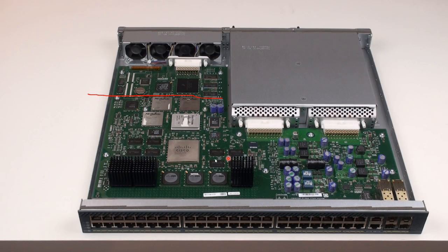On the side, these are all probably memories like SRAMs, those GSIs, or the Samsung chipsets we have here. They are all memories, probably cache or buffer or something. And here we have some more chipsets which are proprietary to the function of this particular switch model. I think these are network processors, for doing different functions like faster packet manipulation, or changing the information in the packets, or specific functions of this particular Catalyst 4948, which might be related to the whole Catalyst 4000 series.